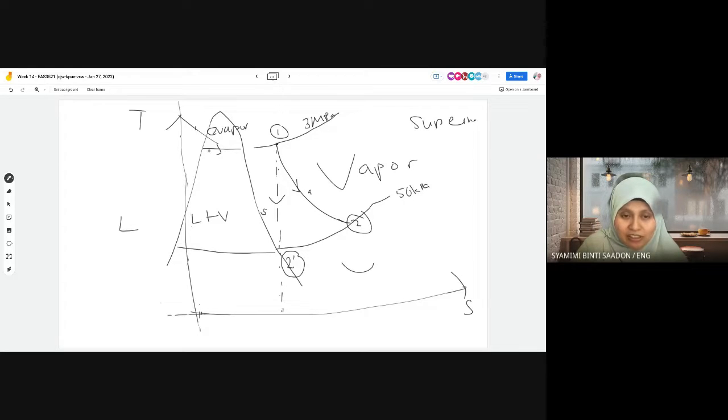The evaporator's function is to evaporate. So normally we will try to evaporate until it becomes totally vapor. That means the state of the fluid at the turbine inlet is vapor, or at the saturated point here, saturated vapor. This is the saturated line. So that's why we use the superheated water table. We consider that it is in the vapor state, totally vapor phase. Okay, thank you, Carol.